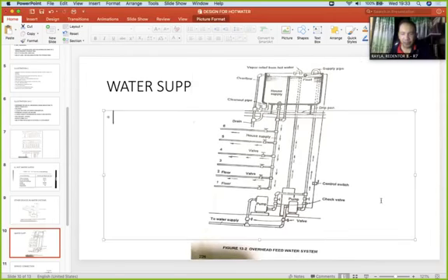Okay, we have three kinds of water system: overhead feed. No? So this one is overhead feed. Sa taas mo galing. We have centrifugal pump. So it's called overhead feed because you will supply water up to the roof deck or the highest part. Overhead tank. We call it the overhead tank. So we'll store the water here. And then after that, you'll feed gravitationally. But sometimes you can use a booster pump here. So the even distribution of water will flow.